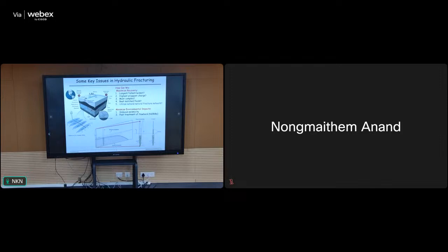And so what we'll talk about is static gas fracturing, the ability to create complex fractures, the ability to transport proppant along those fractures and then examine their permeability, and also then talk about the potential that in the case where we can drill more inexpensively than we can fracture, then perhaps we can use narrow diameter wells with explosive gas fracturing to create volumetric permeability, which is able to obviate some of these problems with the rapid decline rates that we see within fractures.